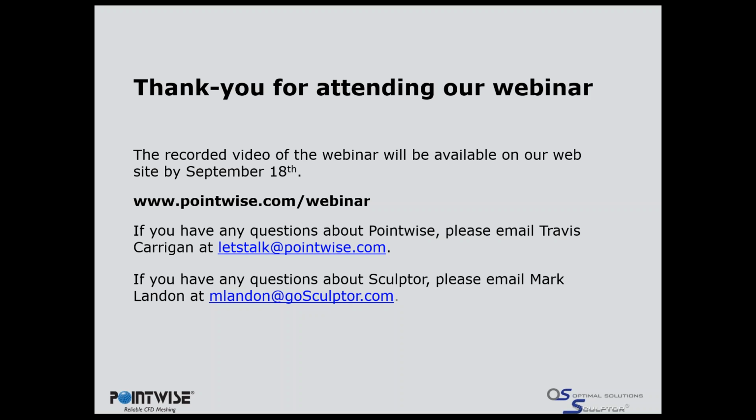And that was, like you said, a separate domain. Now, behind the vehicle, we actually stuck in an isotropic block, a TET block, with refined elements. And so we were able to add that as a face to our larger unstructured block so we could maintain that cell size downstream.